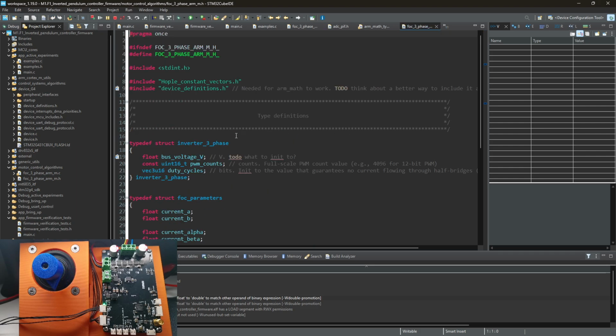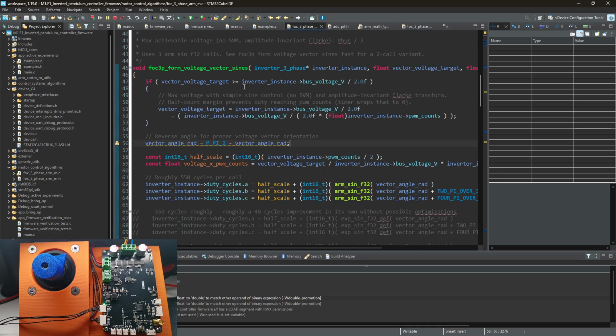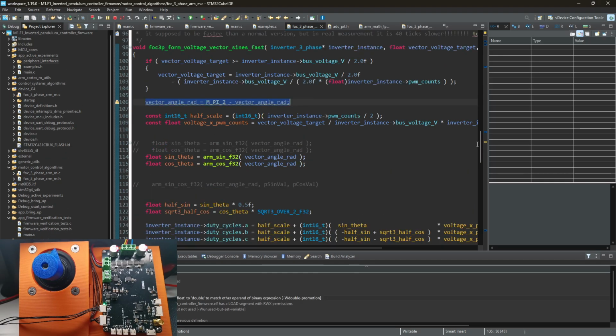This is a huge deal actually. Let's add the file we need. How did I not catch it before? And we should change the floating point unit to F32 because currently it is double. And doubles are not very healthy for microcontrollers. Same thing.